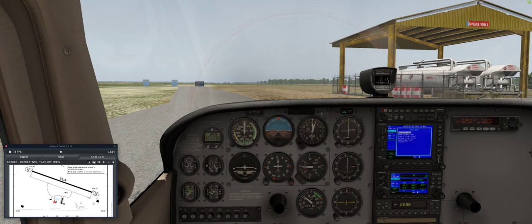The airport you're at should be the active leg. If you had just programmed this in, it would have the airport you're sitting at here, and you'd have to put the rest in, and the airport you're sitting at would have the magenta arrow, meaning it's active. So by me starting this and then restarting the sim, that kind of threw things off. If you were doing this, you'd put the first waypoint in, and you do that by highlighting over that.